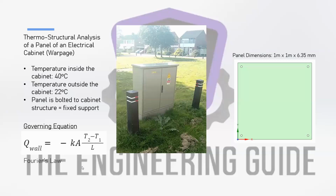And the governing equation for that is Fourier's law, which says that the total heat flux is equal to the negative of the thermal conductivity times the area times the temperature difference divided by the thickness of the plate. I have two videos dedicated to the topic of thermal conduction, which analyze the thermal conduction through one solid plate and the thermal conduction through a composite plate, which is analogous to an electrical system with resistances. I will link those videos in the description below if you guys want to explore this topic a little more. However, I will show you guys quickly how to set up the thermal conduction of a plate in this video, because we do need the thermal loads in order to do the structural analysis on this panel.